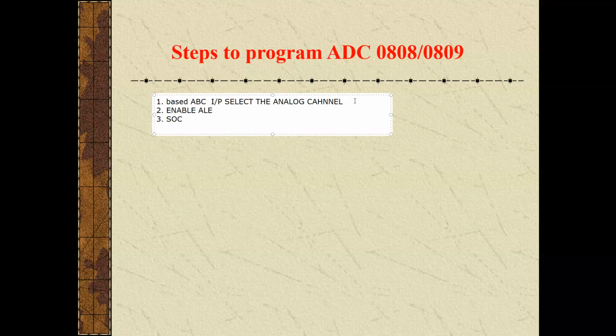Then after that, what do we have to do? Observe the EOC, end of conversion pin, to check whether the conversion process is completed or not.